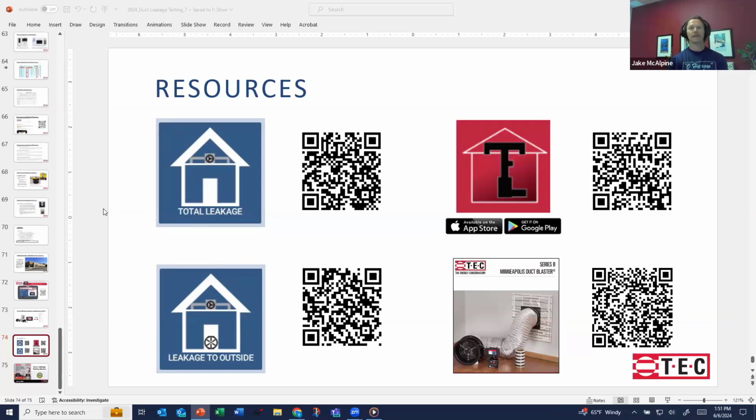Practically, what happens is the size of those registers are so big compared to the volume of air moving down them, it makes it very difficult to maintain anything close to an even pressure along a run of ductwork. It'd be similar to having windows or doors open in a longer house, basically. You get pressure drop from those big holes. So sealing them up makes that test a lot more feasible.